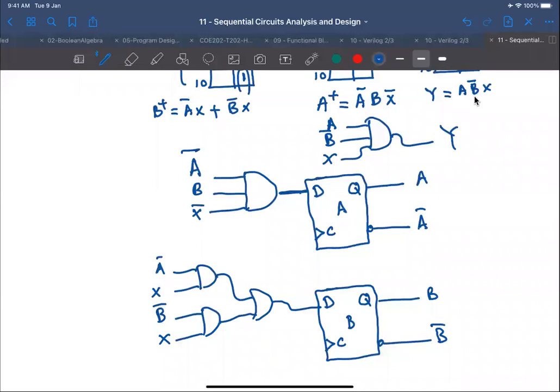Yes. There is an important thing that we missed here, which is the clock. Excellent. Yes. So the clock must be annotated. Otherwise, your flip-flops will not work. You have to connect the clock input to the same clock. They have to be synchronized by the same clock. Both of your state variables have to be synchronized with the same clock. Otherwise, your assumptions will not work as expected.